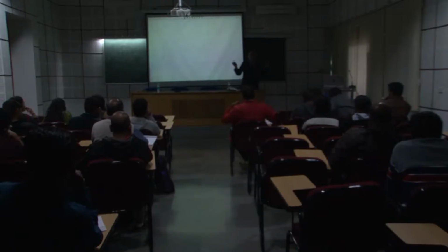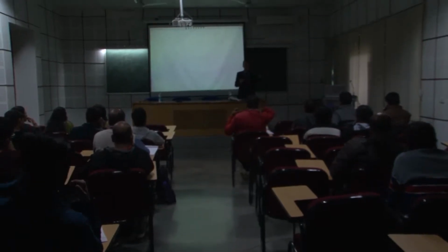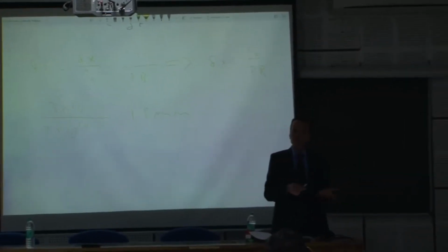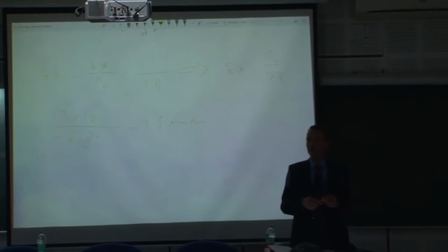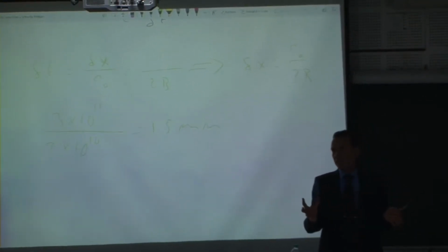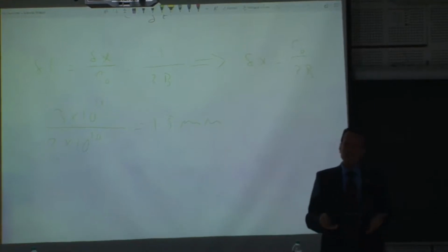If you have a field effect transistor, what is the difference between a FET working at a couple of hundred megahertz and a FET working at millimeter wave? The structure is the same. The only thing which you ask for is that the flight time of an electron or of a hole from source to drain should be much less than a period of the signal you are dealing with.